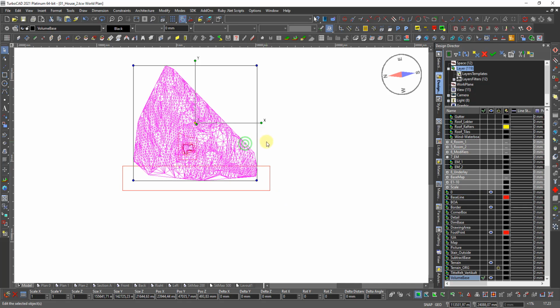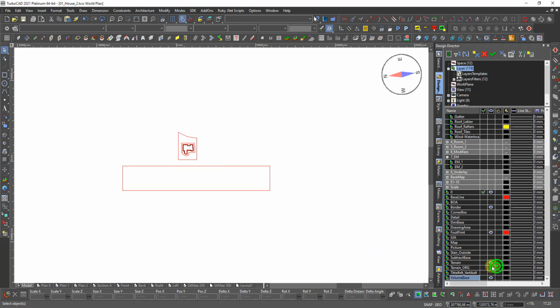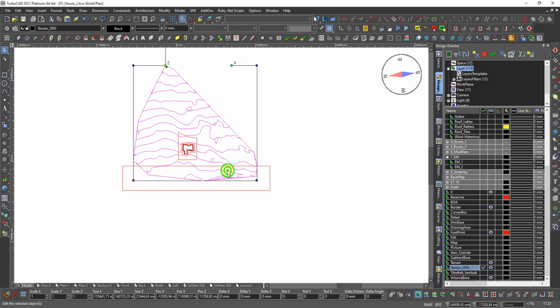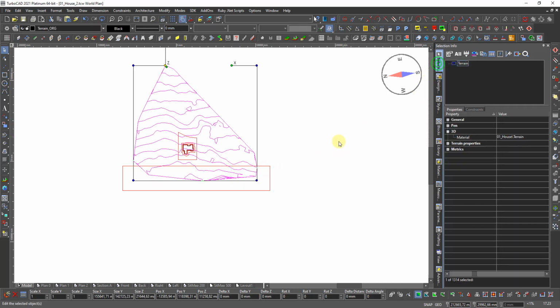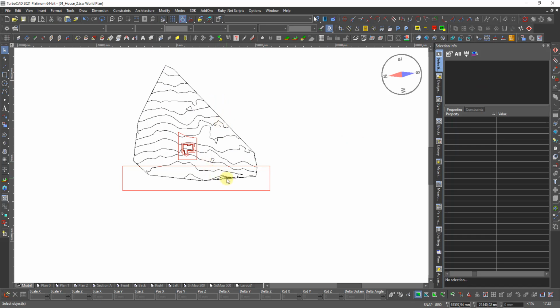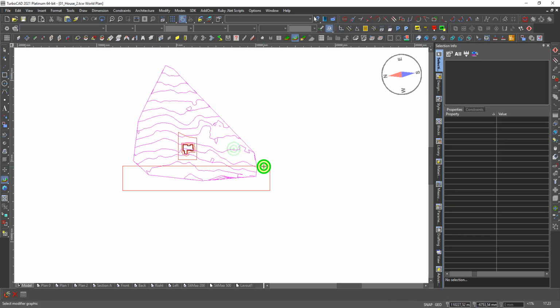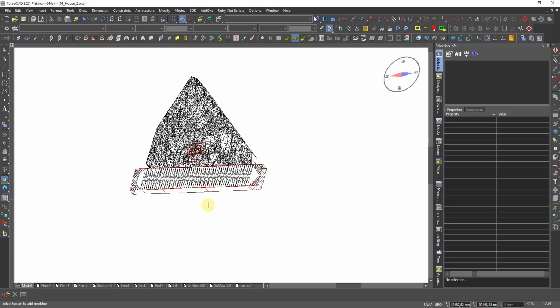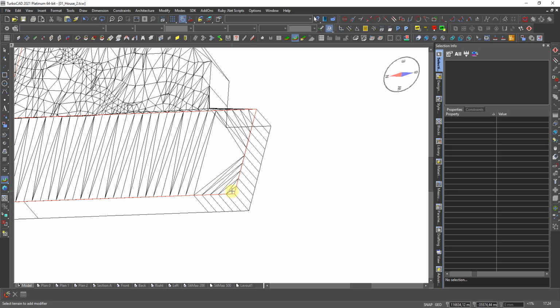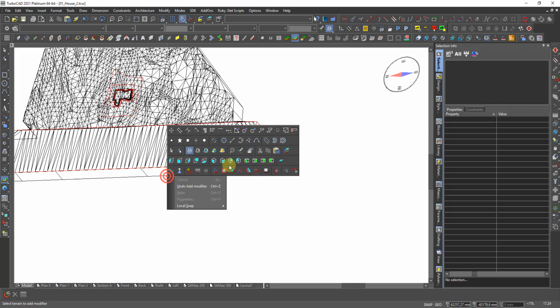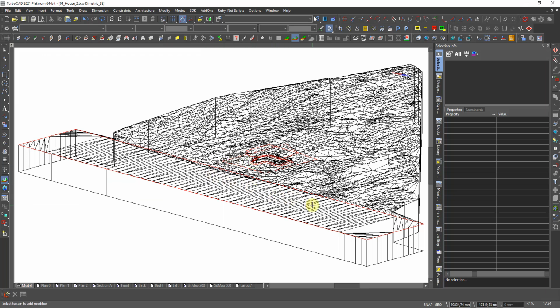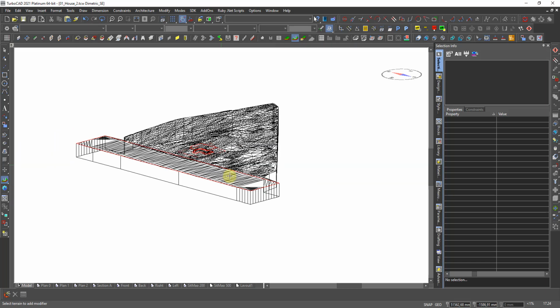Then we delete this one, and I open this. This is still a terrain, isn't it? Yay. So I want to take away this Rocky Mountain or whatever we call it. Matterhorn. And I use this terrain modifier. I select the terrain, I select the modifier, and now it's gone. So then we don't see it, it's flat there. But this goes deeper than what I have. So I see it from here, and now you see this mountain going up. The thin edge is not here anymore.